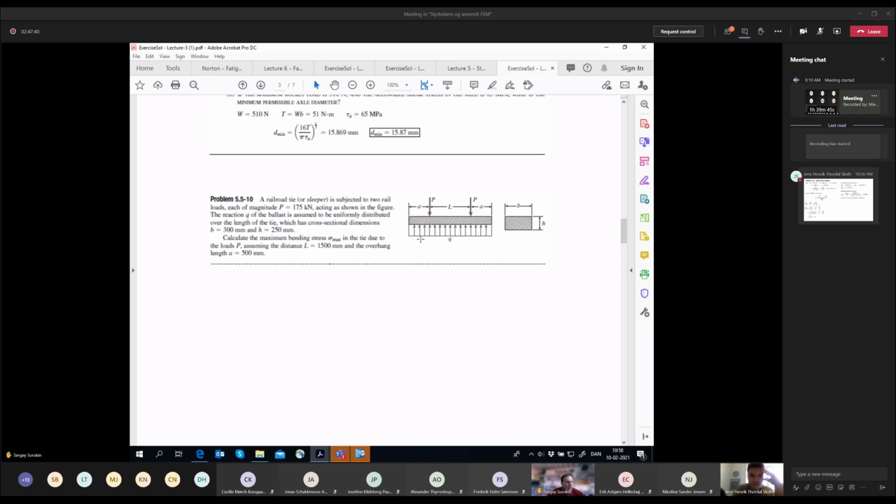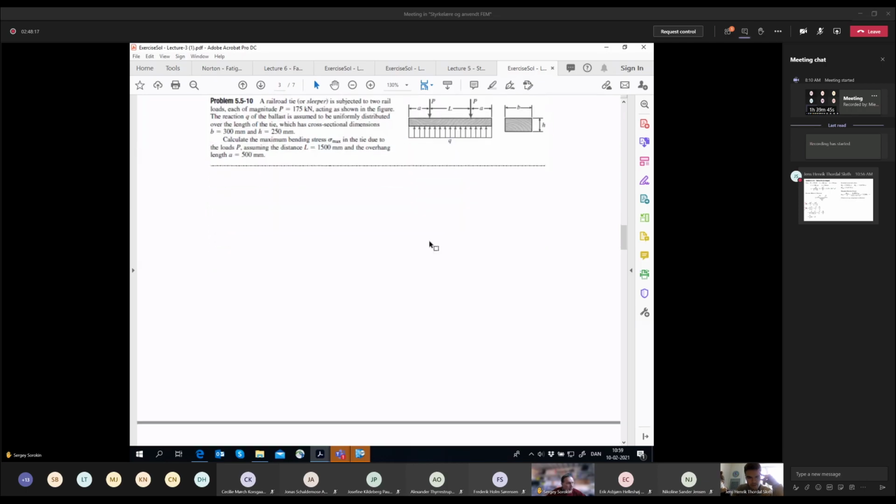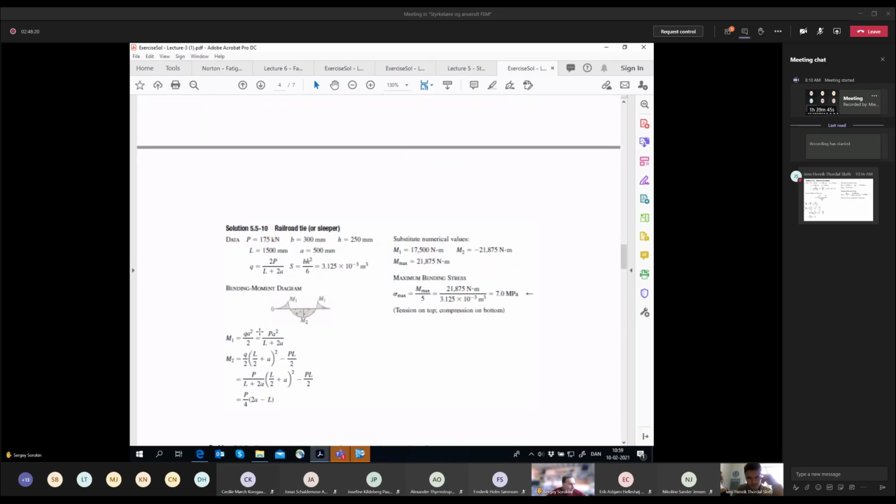You do the cut here, and then you sketch this small piece, and this piece is loaded by a uniform load, and at this cross section you have the moment acting in this direction. Then you write the formula for the moment, and it will be qx squared over 2. Then you come to the point x equals a, substitute a instead of x, and you get this result, qa squared over 2.